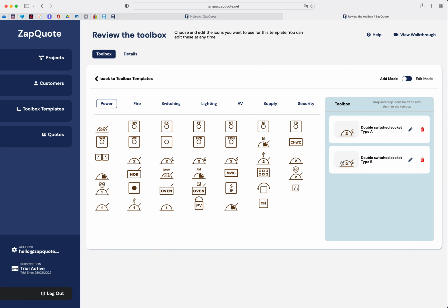There we go. A couple of other icons I'd like to point out to you is we have a specific one for your boiler supply, your photovoltaic isolator. We have your immersion supply. There's your intruder alarm. This is your multi-isolation point. This is for something like inside a kitchen where you're isolating your dishwasher, wine fridge, washing machine, your extractor, fridge freezer, for example, hot tap.